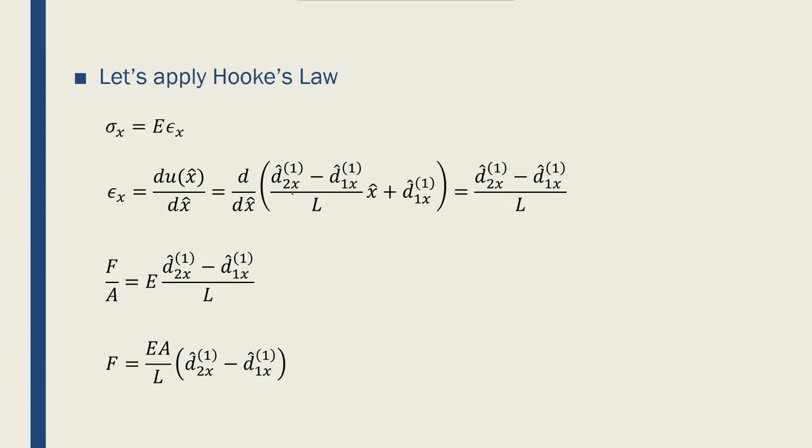Now that we know that, we come to Hooke's law. Stress equals Young's modulus times strain, and stress was basically Fx over A, and strain is delta L over L. Another way to define epsilon or strain is to say it's equal to the gradient of displacement with respect to x, or the distance.